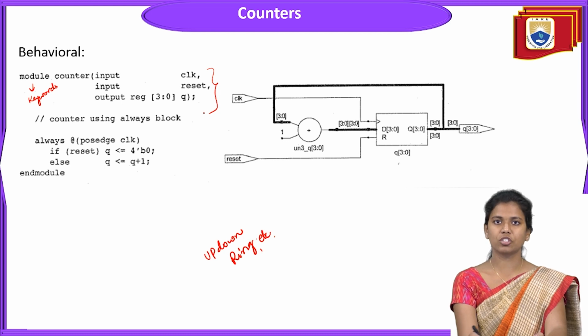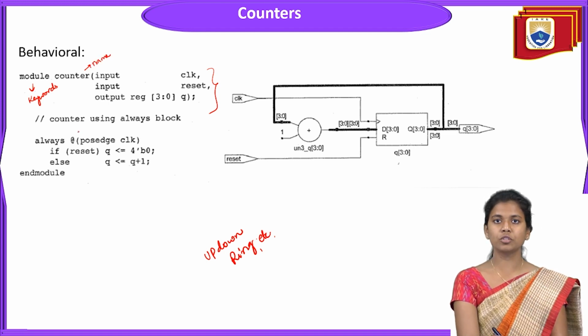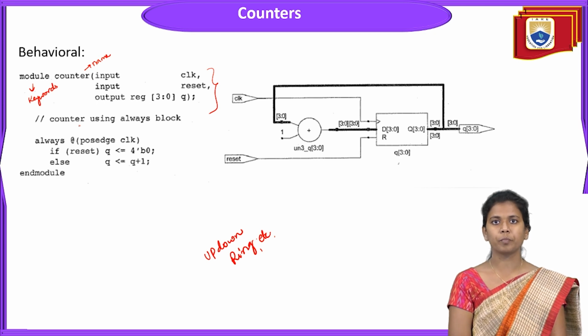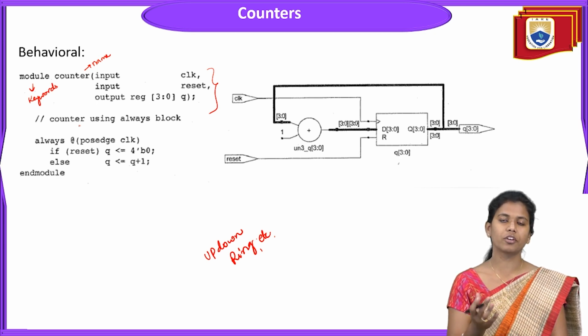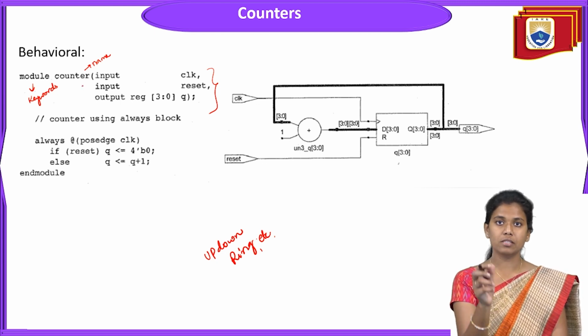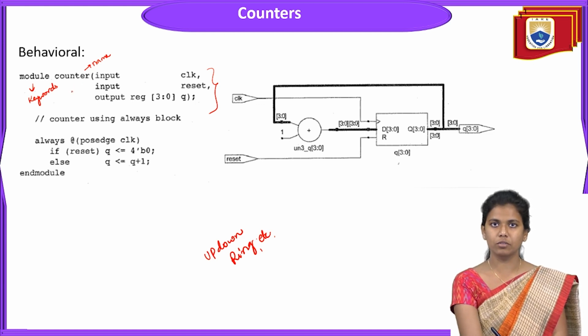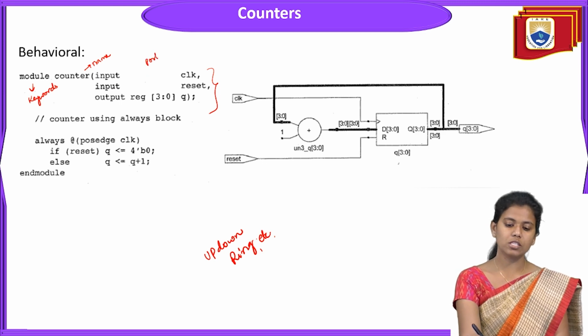In this initialization section, we mention the module that you are considering. Always start the program with the keyword module, and then the name of the logic or combinational circuit that you are considering, here counter, followed by the port list.